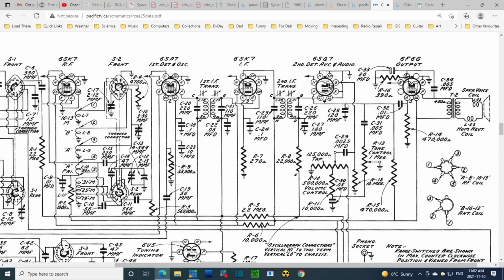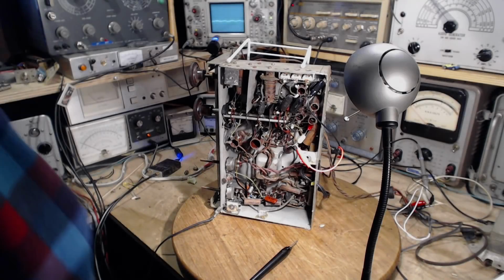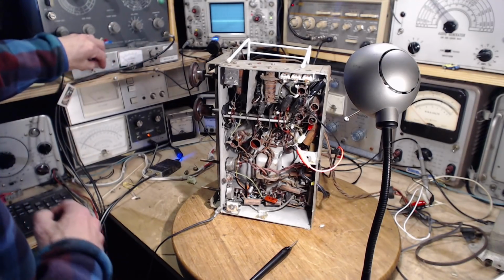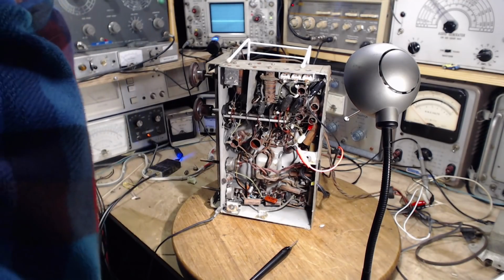So we need to check the impedance or resistance of the plate circuit to the chassis. Then we'll check that capacitor. And then we need to cut this resistor out and see what's going on with it. So we want to check C28. Don't really have to know where it is, not unless there's trouble. So first, plate resistance, then this resistor is next. Okay. Power off, or I'm going to have some really interesting test results.